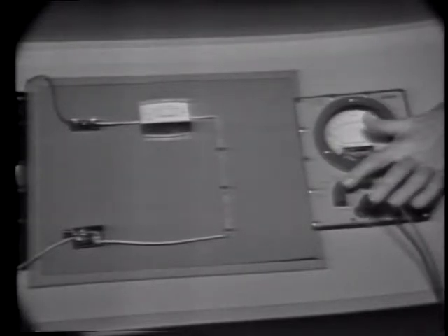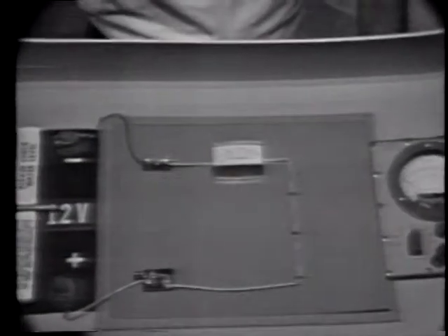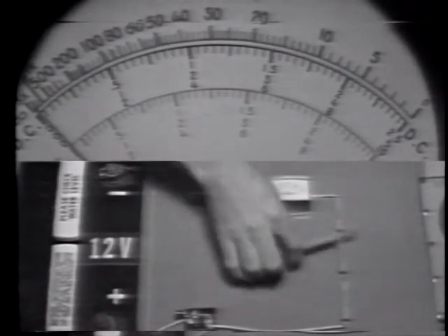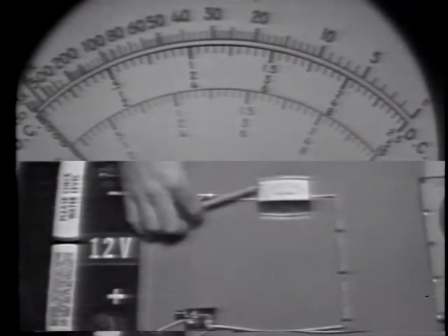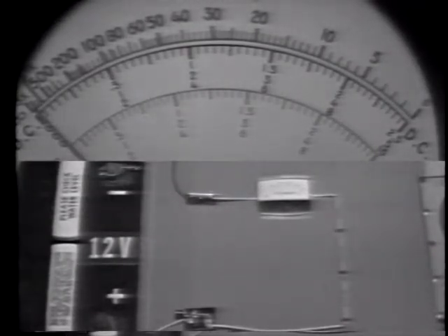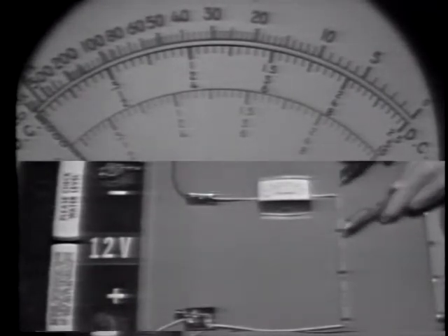Well, let's find out what the voltages are in this circuit. To do that, we'll use the PSM6 as a voltmeter. The function switch is on DC volts, and we'll use a range of 10. Now, we'll use the 10-volt range because the applied voltage is 12 volts, and this 12 volts will be distributed around the circuit as long as a reasonable amount of current is flowing. Okay, let's check across each resistor.